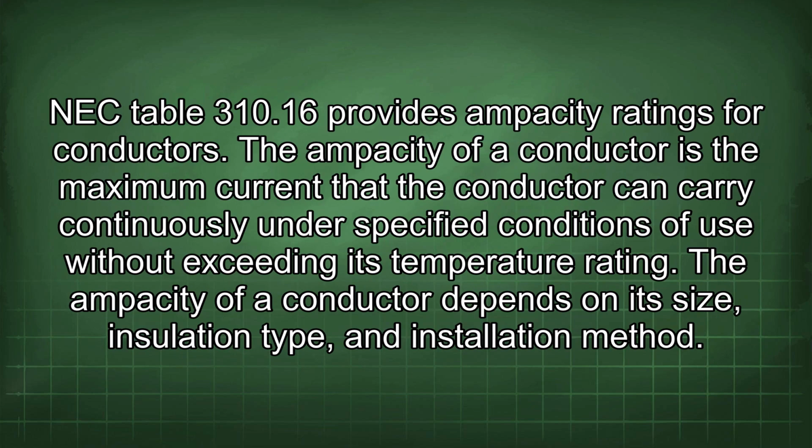NEC Table 310.16 provides ampacity ratings for conductors. The ampacity of a conductor is the maximum current that the conductor can carry continuously under specified conditions of use without exceeding its temperature rating. The ampacity of a conductor depends on its size, insulation type, and installation method.